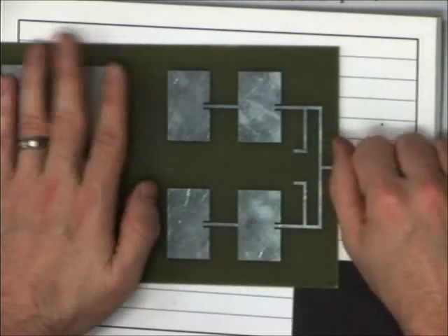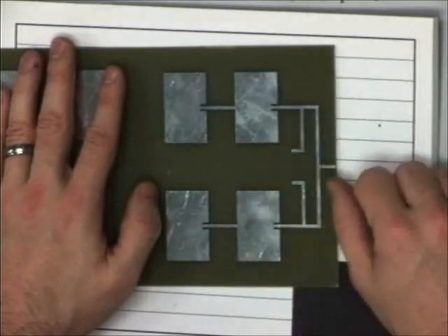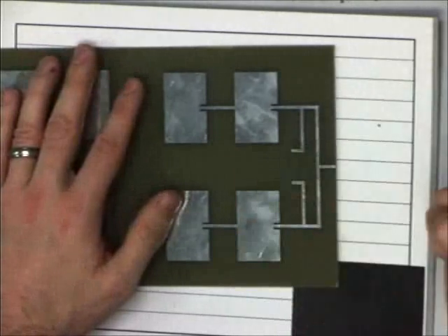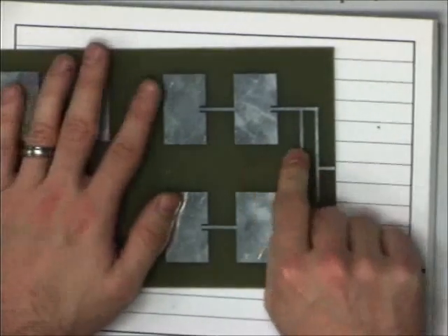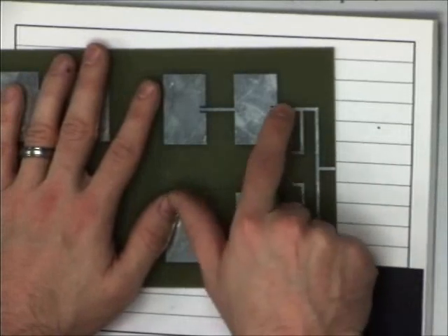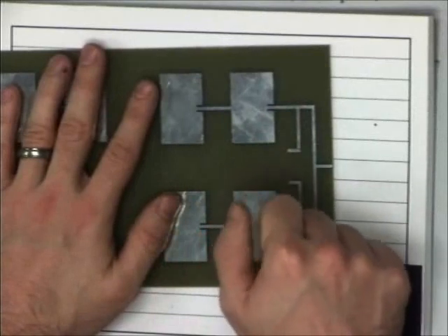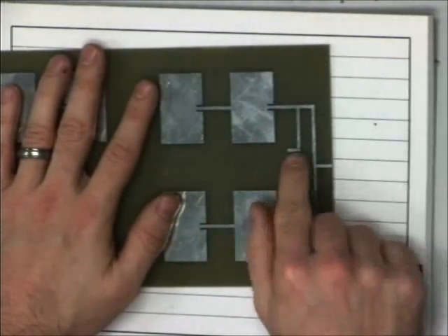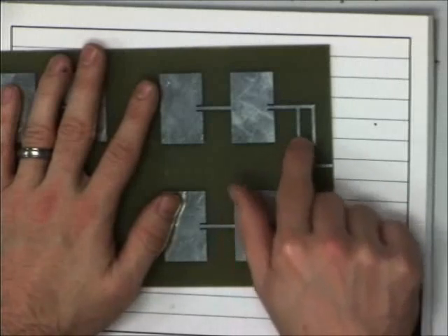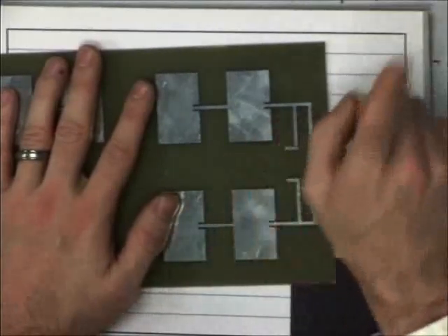In fact, in microwave design lab, a PhD level class here at Georgia Tech, students actually build a lot of these devices, and they have to tune them and match them. They'll put on stubs, and I like to call them desperation stubs. They don't know exactly how much they're going to have to tune out, so they just throw a long stub there. Then they put it on the network analyzer, see how well it's radiating and how well it's matched, and then they take an X-Acto knife and desperately scrape away the length of the stub until it's tuned perfectly, being careful not to scrape away too much, because you can't go back, right?